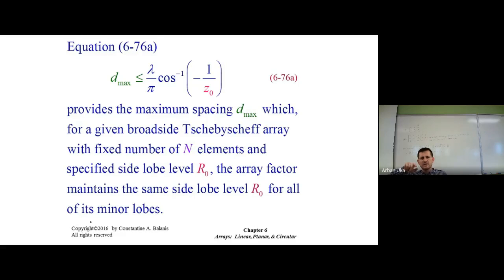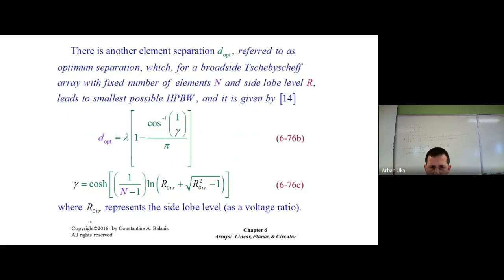Otherwise, if this condition is not satisfied, we're going to see an antenna which has a major lobe, and the minor lobes are going to have different ratios with respect to the single largest lobe. So it's an element of elegance, an element of having the antenna being equivalent to some degree, because all the minor lobes are going to be equal to each other. Now, this was Dmax.